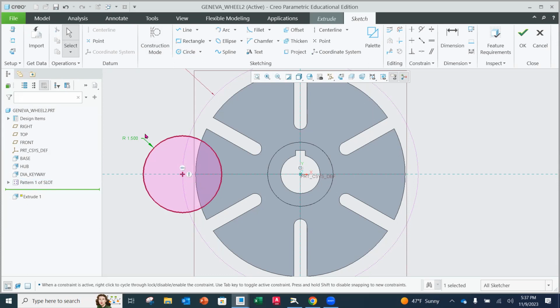I haven't been enforcing that or making it an emphasis, but later on, when we do our engineering drawings and the dimensions come in, it'll remember if you did it as a diameter or as a radius. So do yourself a favor, because if it is being called out as a radius, you want that dimension to come in automatically. You'll have the ability to change it later on as well, but why not do it here? Okay, so that one's in here.